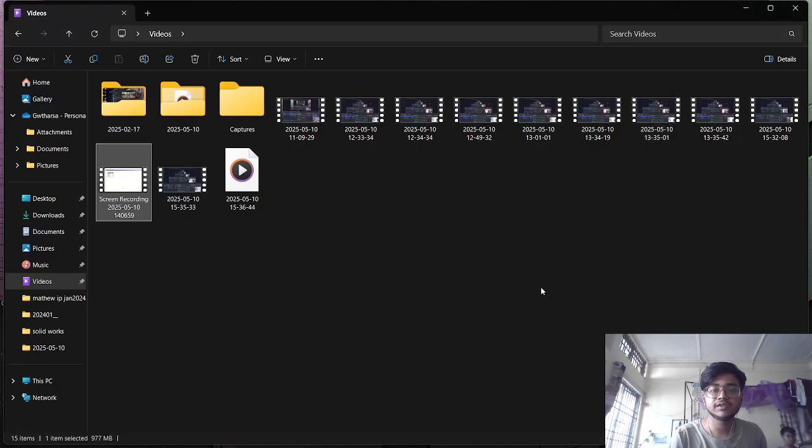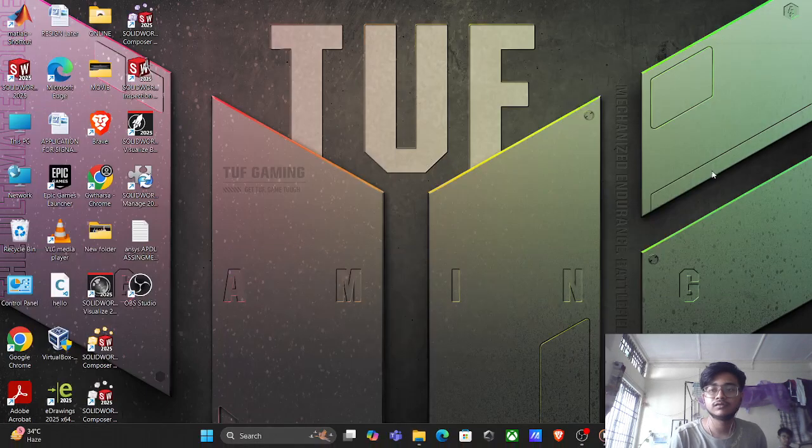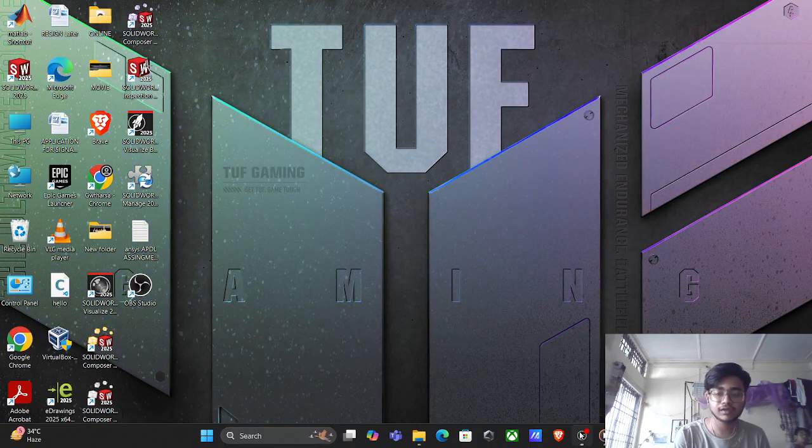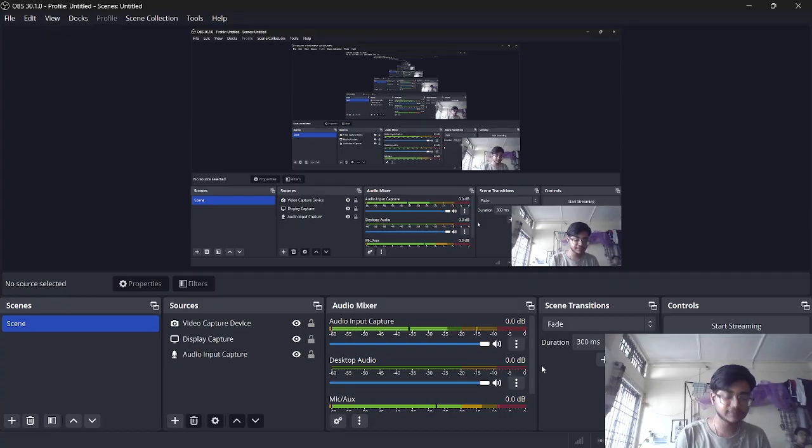Okay, so with this we can say that we have successfully shown how the temperature varies and how the Rayleigh number also affects it. Increasing Rayleigh numbers intensifies convection effects, enhancing heat transfer efficiency but reducing temperature uniformity. For engineering applications, optimizing the Rayleigh number can balance efficient heat removal with acceptable thermal gradient depending on the system.